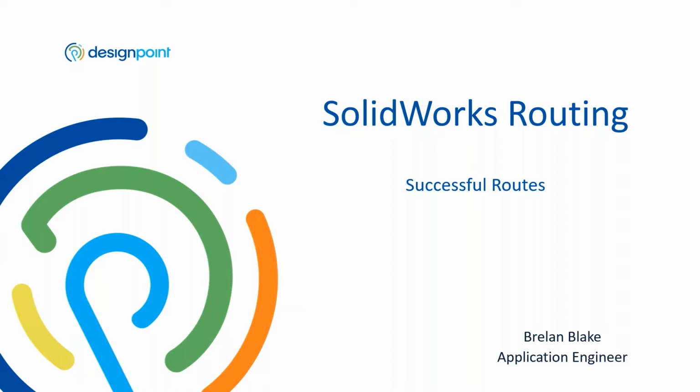But that's one of the number one ways. That's your option one for creating any kind of a route component. So there are already default components there, and what you can do is just take one of those components and do a save as, and you would go through the routing library manager to save it out and then change the file name to create your own component.